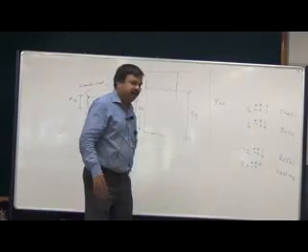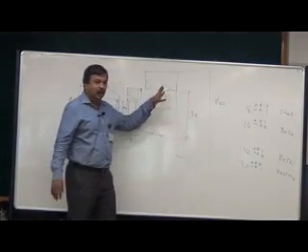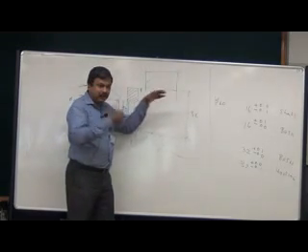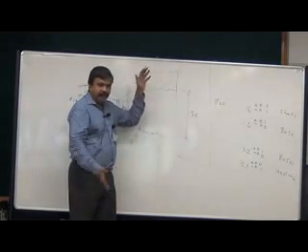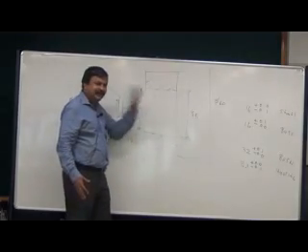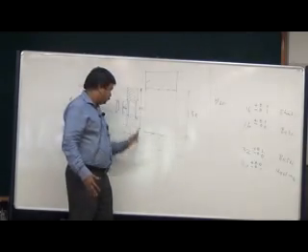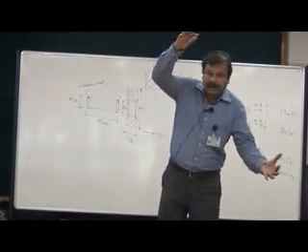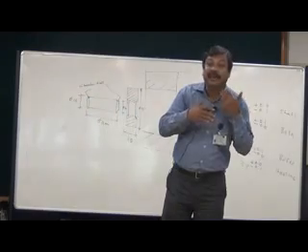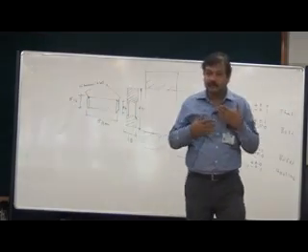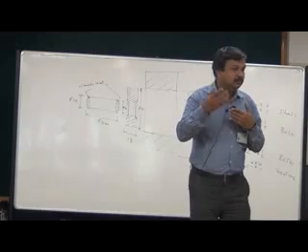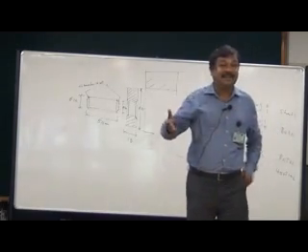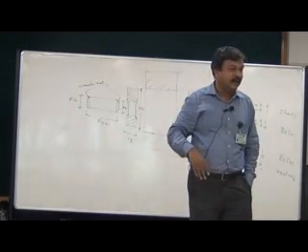The simplest way is, suppose you heat the hole, you heat this entire housing. What will happen? It will expand. Then you insert the bush and allow it to cool. What will happen? It will contract and there will be interference between the housing and the bush.